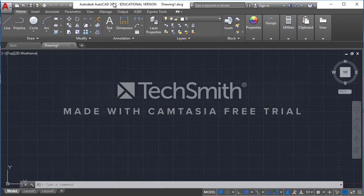The more important part of AutoCAD is understanding the ribbon and also understanding our toolbar, or our typing command toolbar, at the very bottom of the page. So if you go up to our upper ribbon right here, you're going to notice two different rows of commands. The upper one is going to be where you see Home, Insert, Annotate, Parametric, etc.